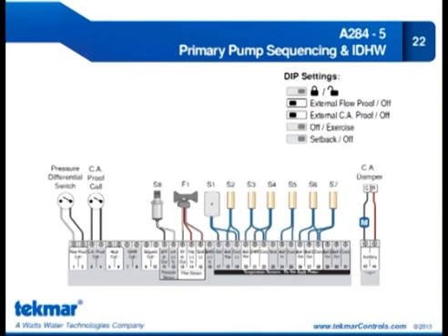Okay. I only have one more question here, and that is asking if you can go over the ways that we can prove primary pump flow. Yeah, and that's, again, if you look at other products, if you have a pressure switch, flow switch, and typically within the boiler itself, those are typically flow switches, paddles, right? We're talking about primary flow, right? So you're going to probably buy an aftermarket switch, and paddles aren't the most reliable. So most commonly we've seen current sensing devices, or you can use a pressure switch if you wish. But those are the most common.